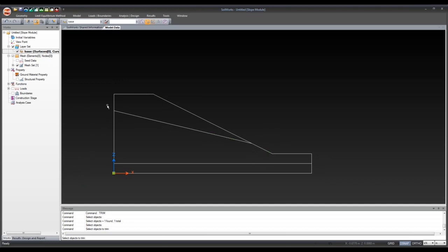So in order for me to assign material properties to these enclosed areas, the program needs to have surfaces for each enclosed area. Because until you do so, the program just recognizes it as a series of lines. You can't assign attributes to these enclosed areas until you create these surfaces. Oh, but another thing I noticed here is that this line,